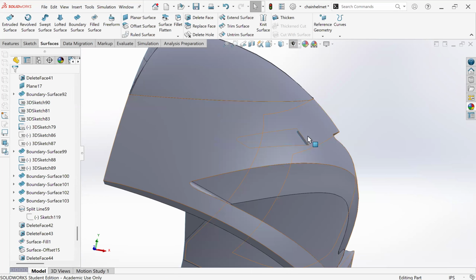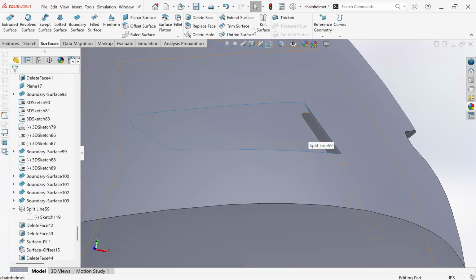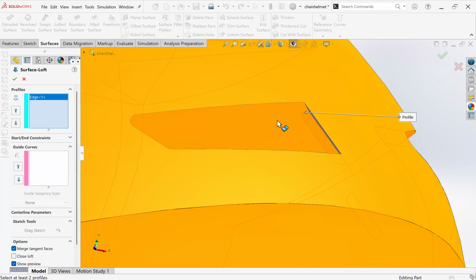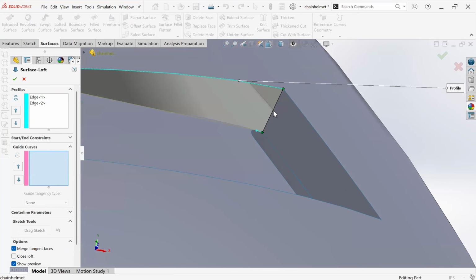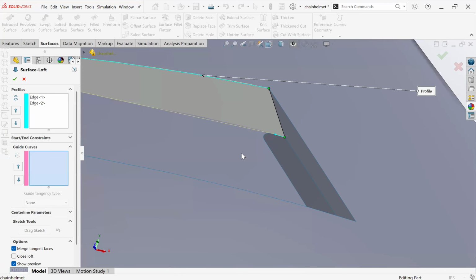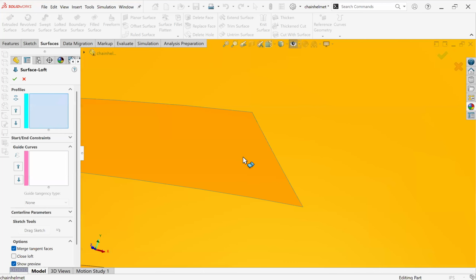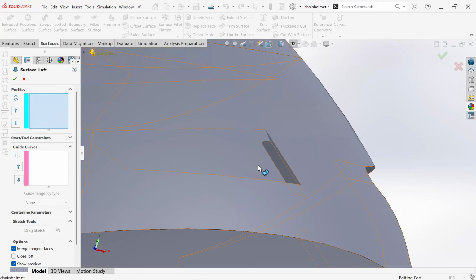And from this side, I have to push this up a bit, so it curves up over here. I do this a little at a time again. Loft this edge to this edge. And I'm gonna pick any edge that we have existing as a guide curve. So it's connecting to that. Looks like I should do this last because this is running into that surface. So here. And try it one more time. If this doesn't work, I'm going to move this hole farther up.